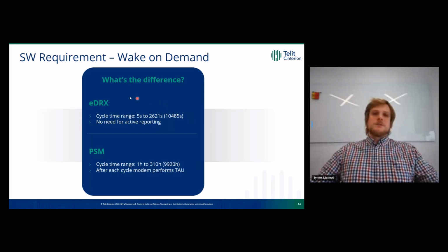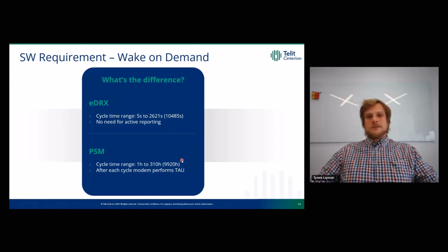What's the main difference between eDRX and PSM? Well, first off, the timing. eDRX is just longer no listen. PSM is longer complete sleep. But the key difference is at the end of each eDRX cycle, there is no need for active reporting. So modem does not tell the network, hey, I'm back. No, modem is just simply sitting there and listening if there is any information from the network for me.